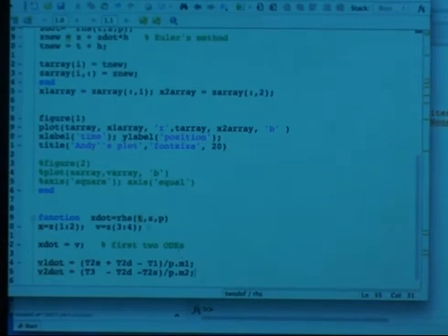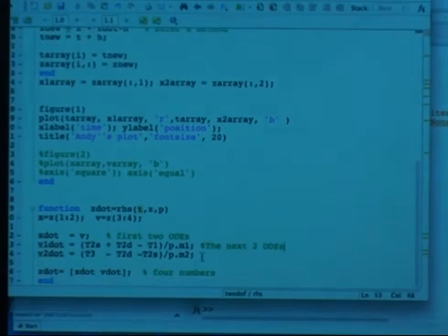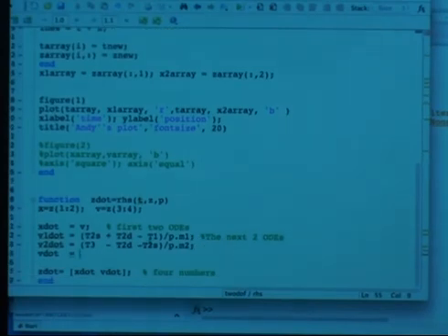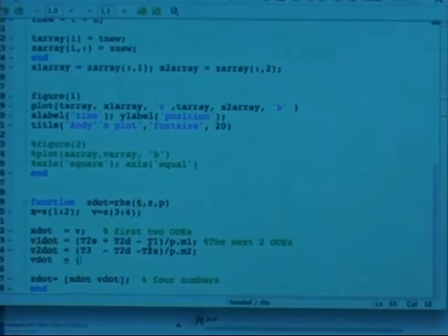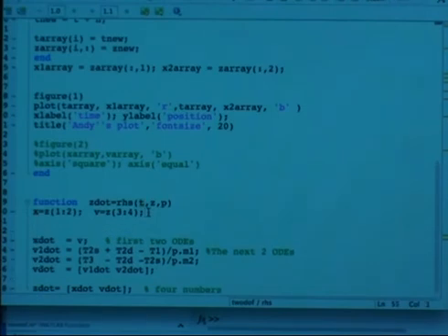So I can calculate these tensions somewhere. To keep all the differential equations in one place, I'll just put those all in a line there. So here's all 4 of my ODEs. Here's the next 2 ODEs. And then we're all done except I've got to figure out what v dot is here. There are various ways to do it. When in doubt, my suggestion is to put more lines of code which are shorter, because it's easier to debug and figure out what's going on. It's easier to read. So v dot is a mixture of v1 dot and v2 dot. And then I've got this ready to go. So all I've got to figure out now is what these T's are, and I've got my whole right-hand side.